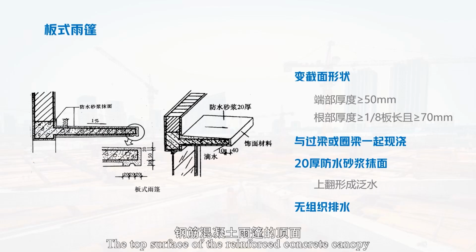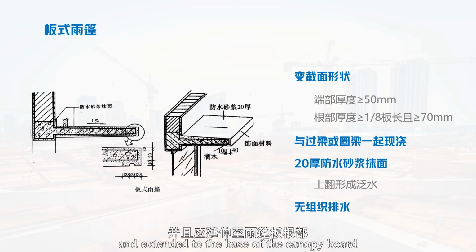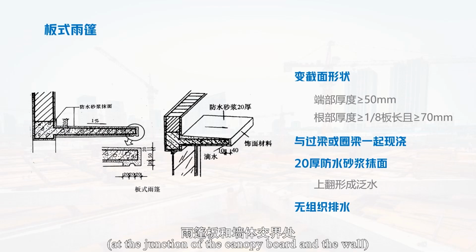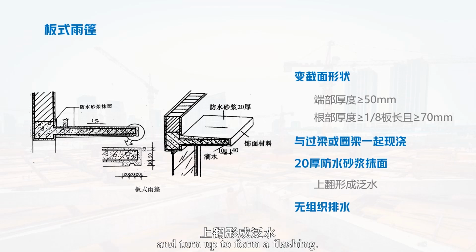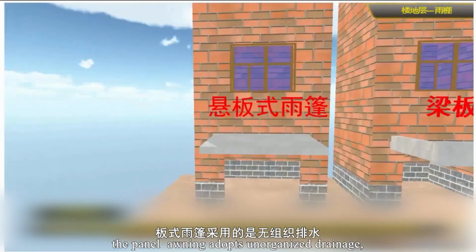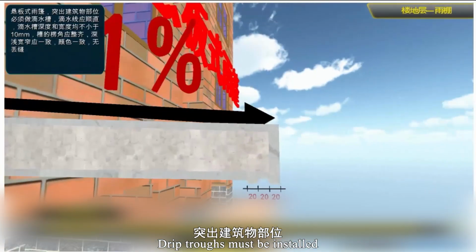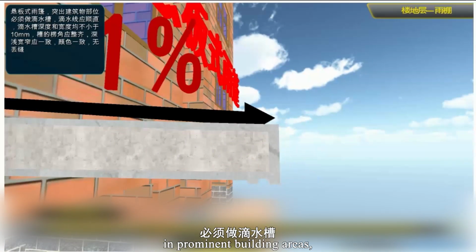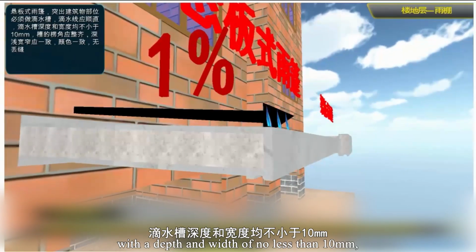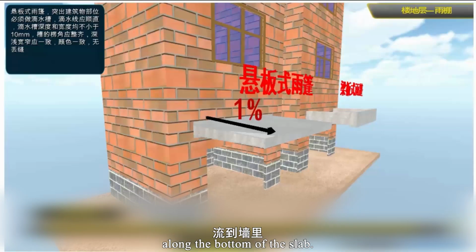The top surface of the reinforced concrete canopy should be coated with waterproof mortar, extended to the base of the canopy slab at the junction of the slab and the wall, and turned up to form a flashing. In the picture, the slab awning adopts organized drainage with a 1% drainage slope for outward drainage. Drip grooves must be installed at the prominent edges of the building, with a depth and width of no less than 10 mm, to prevent rainwater from flowing along the bottom of the slab into the walls.